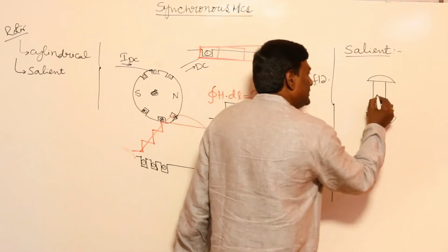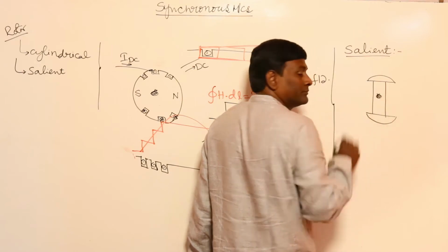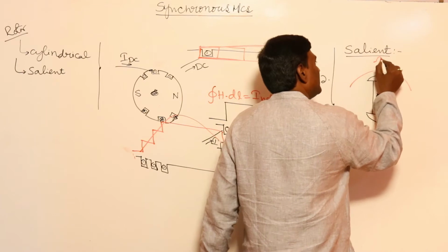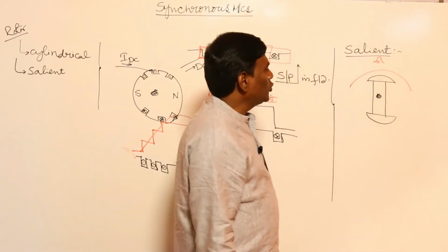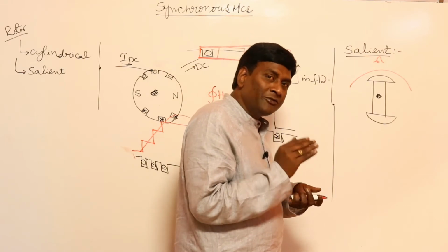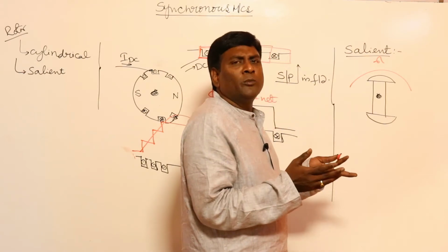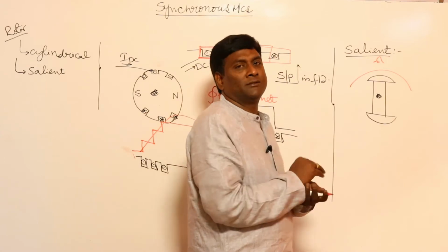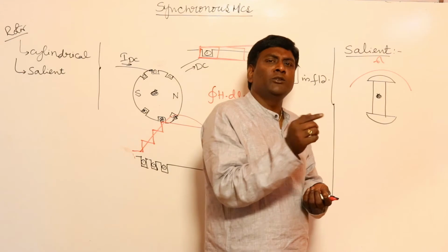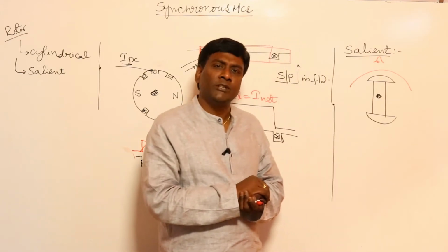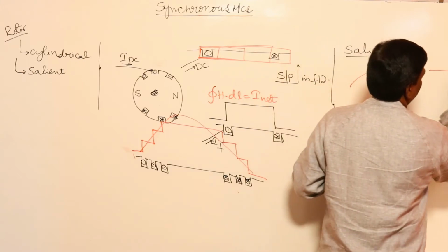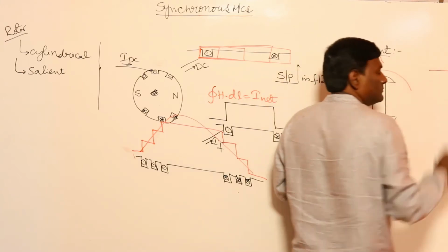Okay, so in this salient rotor, upon this, the stator will be there. How to make the field flux a bit better sinusoid? Because if I can reduce harmonics in the field flux, automatically the induced voltage harmonics in the stator will be less. Because induced voltage is directly proportional to flux density, if flux density can be sinusoid, automatically the induced voltage in a conductor will be sinusoid.